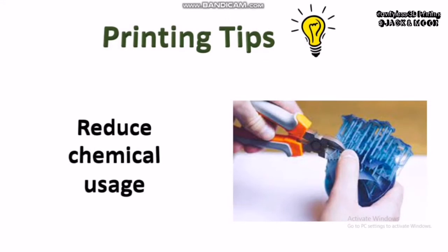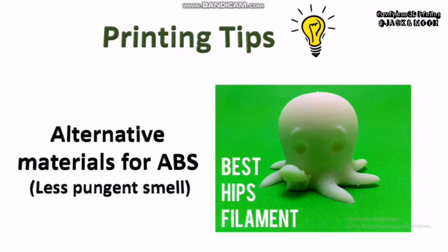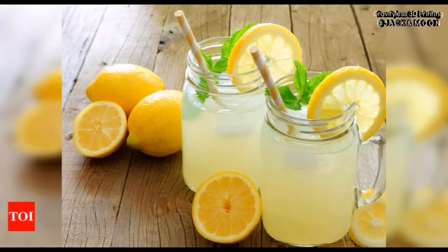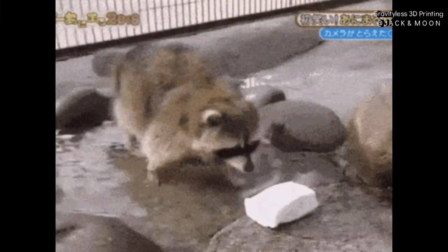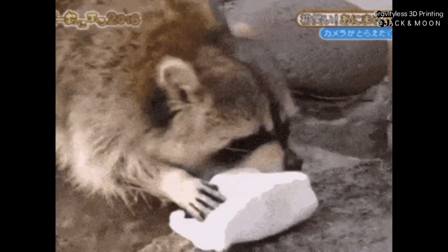HIPS do release odor during the printing, but it is slightly less pungent compared to ABS. Thus, you can use it to replace the usage of ABS. But please be extra careful that your part cannot be exposed to chemicals such as lemonade waters, as it will slowly dissolve.